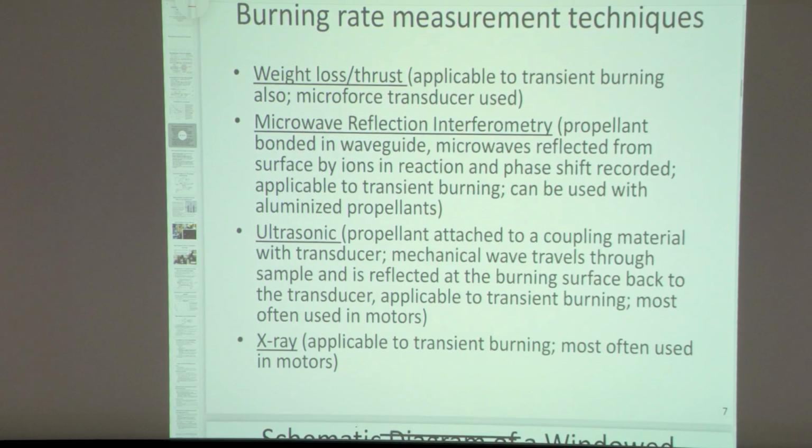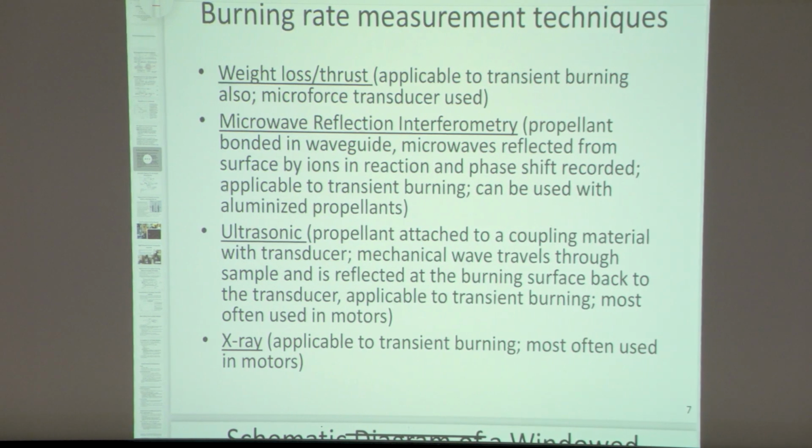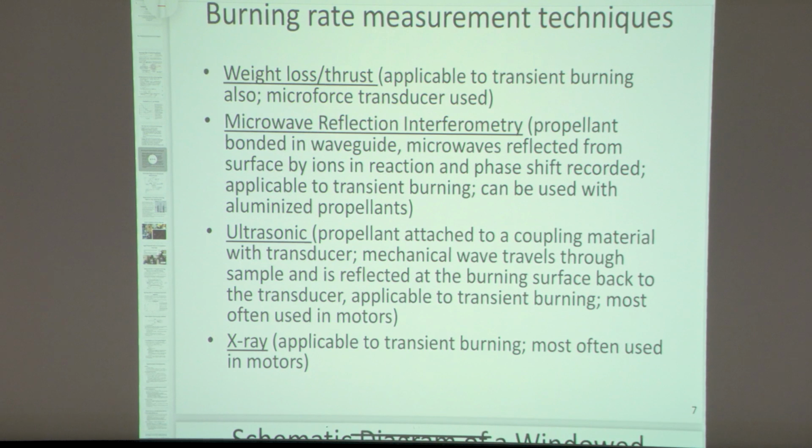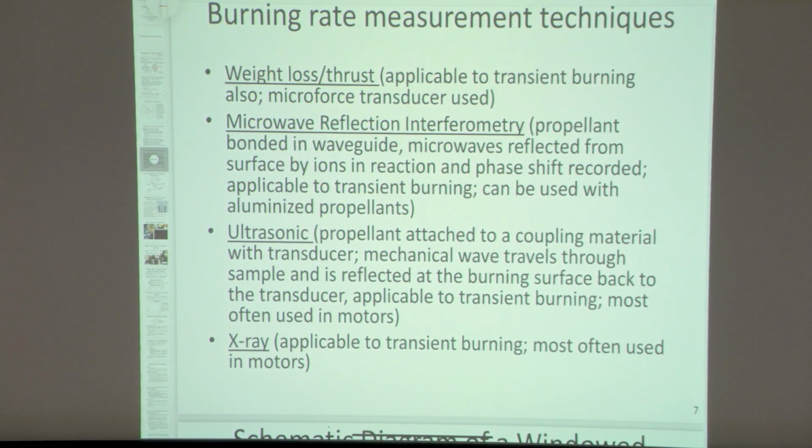I could do something less crude, and this is maybe more for motors or larger systems: I could look at basically the weight lost, or I can measure the thrust. And as I said, it can be applicable to transient burning. I could also use a microforce transducer in measuring this thrust.